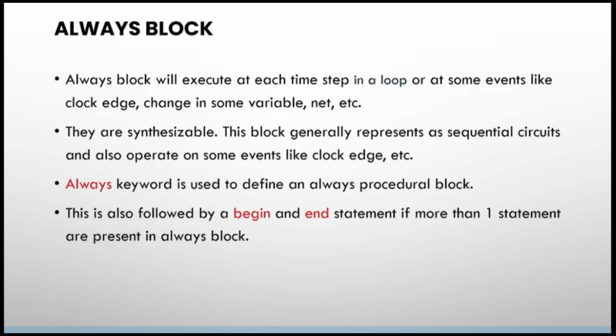Similarly, in both you can write any number of initial blocks and any number of always blocks. If you are writing three initial blocks, all of them will be running concurrently. Similarly, if you are writing three always blocks, all three will be running parallelly based on the delays that you are giving. These are the similarities and differences between always and initial block.